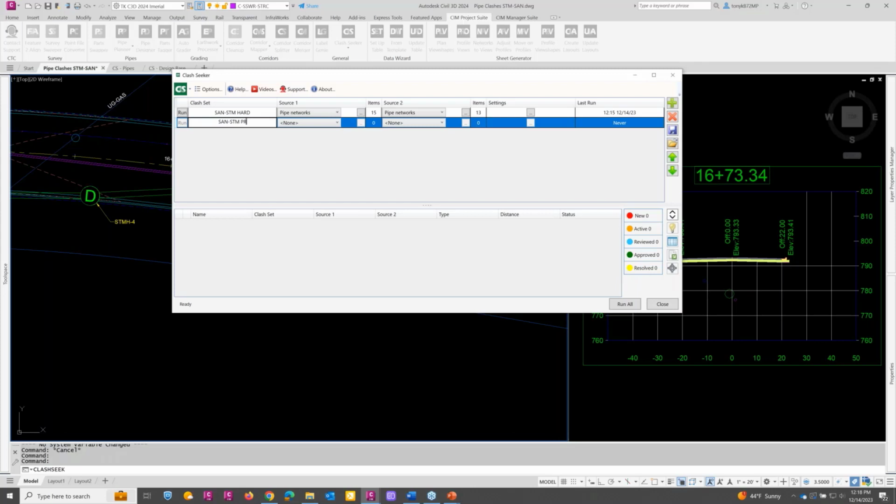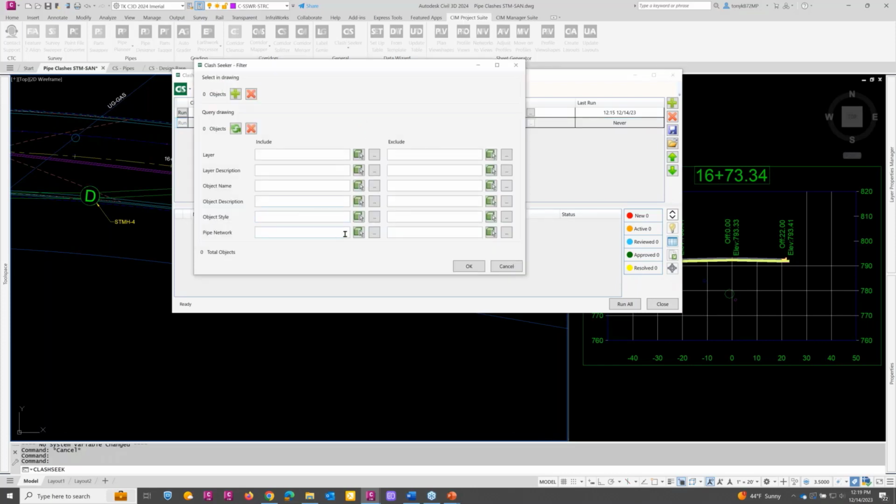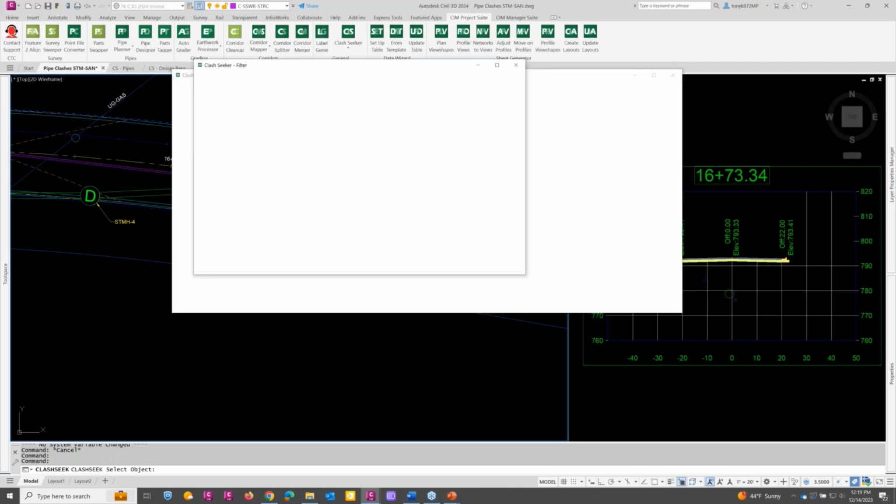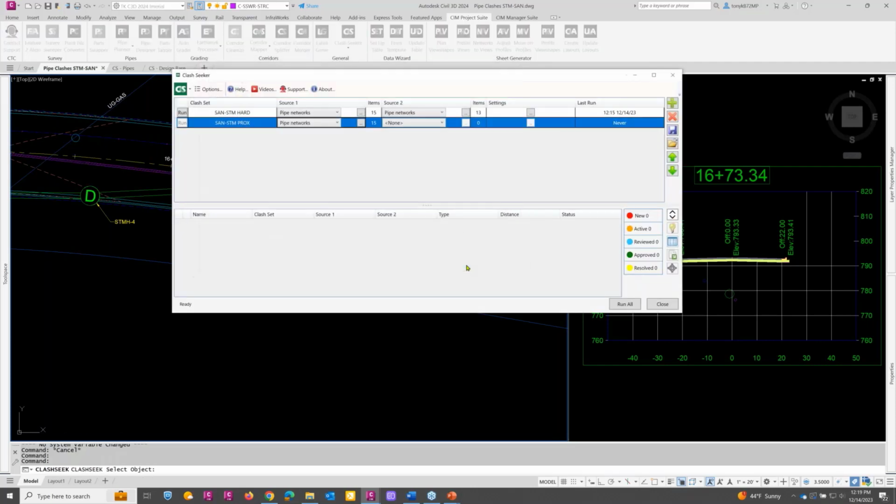I'm going to include prox in this one, so proximity clashes. I have my caps lock on. I'm not used to that. So we'll do the same thing. Go grab it. And I could have copied that one, could have saved it out and brought it back in, so I didn't have to do all this setup, but it really doesn't take that long.